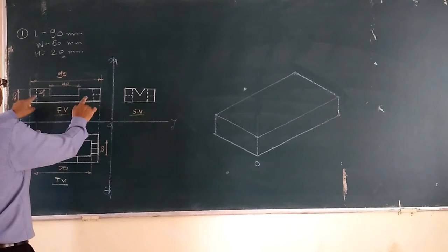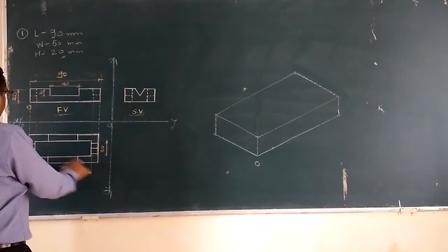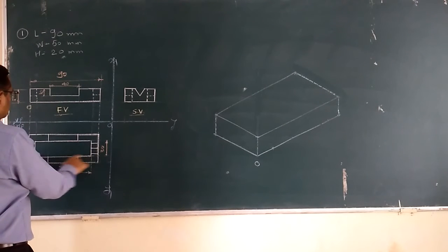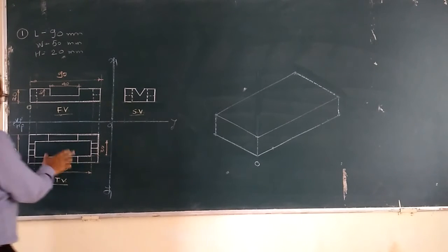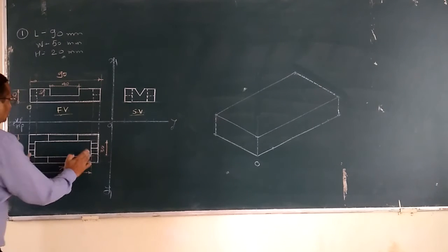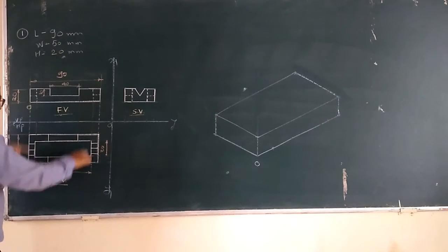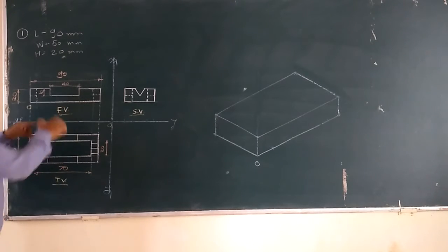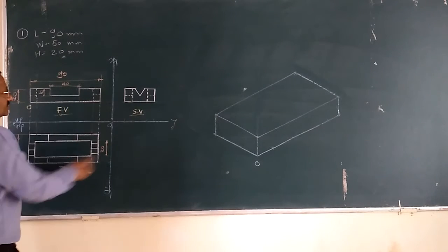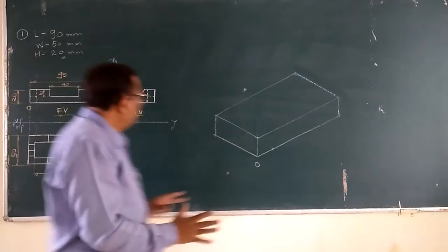Okay, so those dotted lines or dash lines are interpreting. Just see here, dotted lines get projected in top. Centrally, this rectangular part is shown here. First of all, initially just concentrate on this rectangle. What does it mean? Again, a rectangular hole is cut initially in that box, in that empty box. We have to cut a rectangular hole centrally.